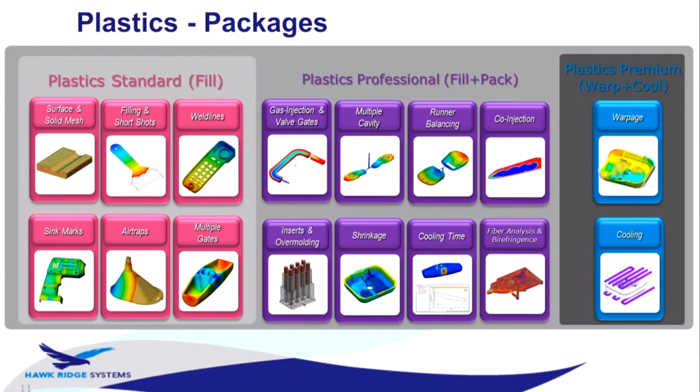SOLIDWORKS Plastics comes in three packages. And in a broad sense, the packages are based on different use cases. So the first one is Plastics Standard. That's going to analyze the mold filling portion of the injection molding process, basically from having an empty tool cavity to a full tool cavity.